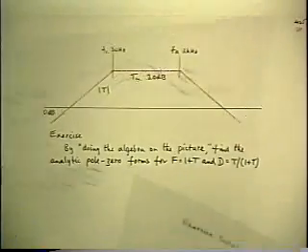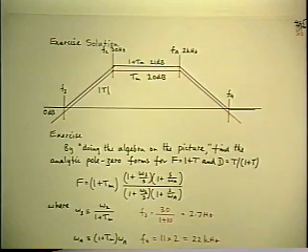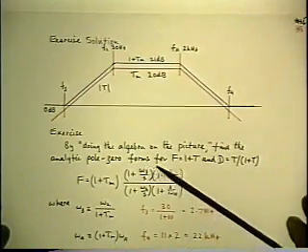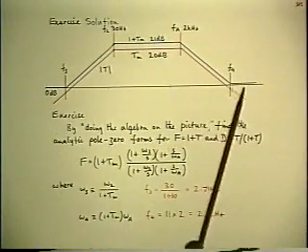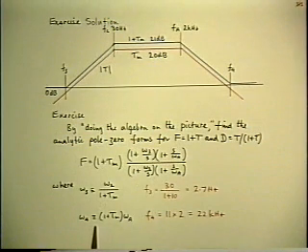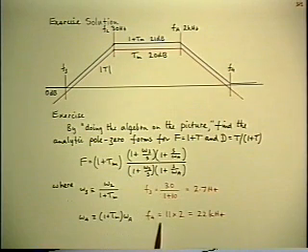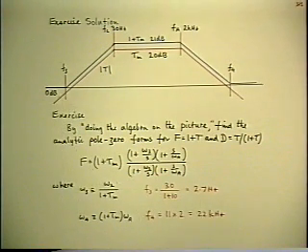And here's the neater version that's already been drawn. Same thing, where I've listed underneath the expression the definitions of the new corner frequencies that have shown up as part of the construction, which is a pair of zeros. And evaluating them numerically, the 0 at the bottom end is 2.7 hertz, the 0 at the top end is 22 kilohertz. So that's pretty straightforward.